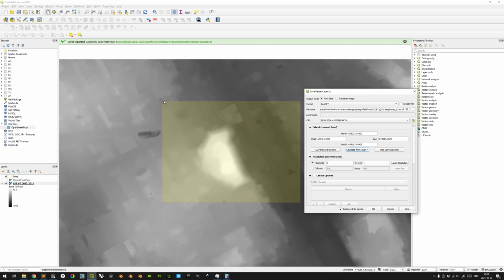This will enter the coordinates of your assigned rectangle, and to retain pixel perfection, these should not be decimal values. Since it is 1 meter per pixel and 1 pixel per meter, and the coordinates are in meters, they should be rounded, and preferably rounded to include the whole meter. So here with the west, we floor this to 1. With the north, we put it to the ceiling of 4. And to the east, we put it to the ceiling of 2. And to the south, we put it to the floor of, no, sorry, of 5. Click OK to confirm.